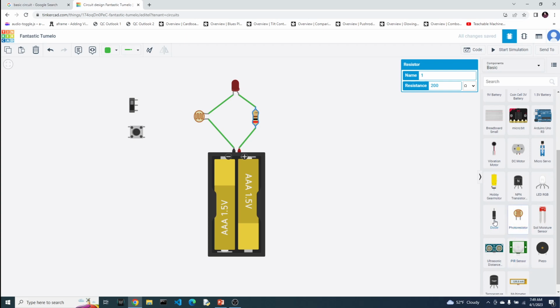I think we can actually take this out and just let this be the resistance. As you can see, it's called a photoresistor. So let's play it out. And at this point, let's raise it. And yeah, I think, and let's lower this resistance down a little bit so it's not competing too much with the other resistance. Let's start again. So notice now that we're in the completely dark area, again, that's what this little slide switch does. It helps to simulate a light source to the photoresistor.